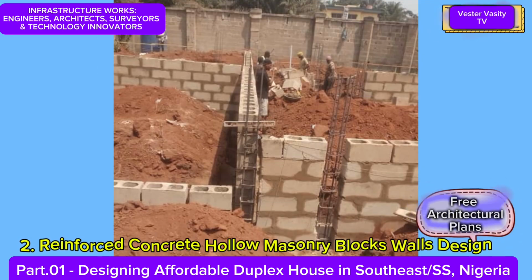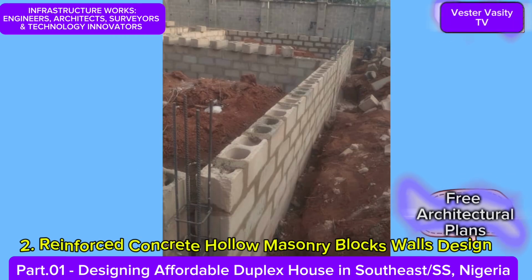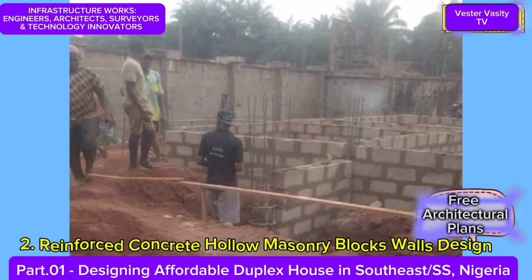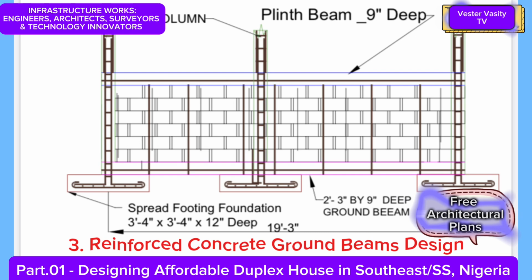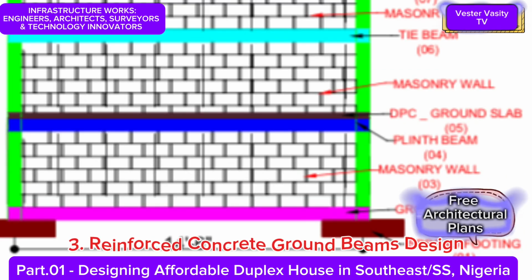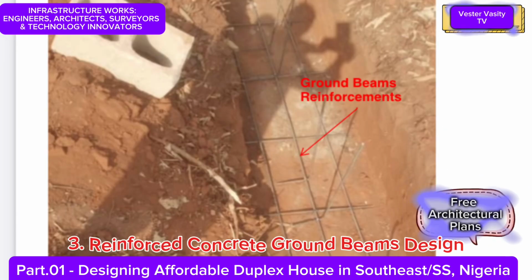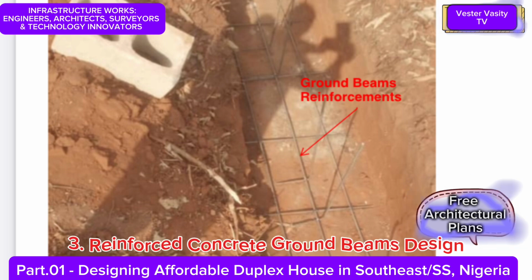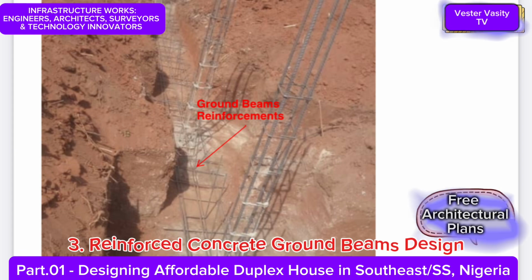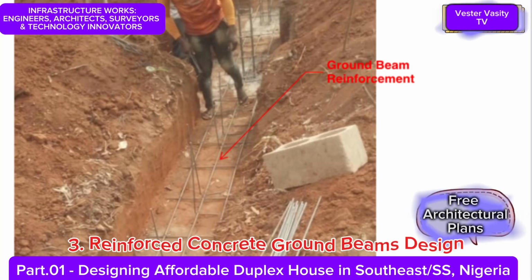The reinforced concrete hollow blocks masonry walls foundation will be discussed separately in detail in another separate upcoming video presentation. The third structural component that you are looking at is the reinforced concrete ground beam foundation. The ground beams are designed to support and carry the weight of the hollow masonry concrete block walls that are placed on top of each of them and are attached and tied to the columns on top of each of